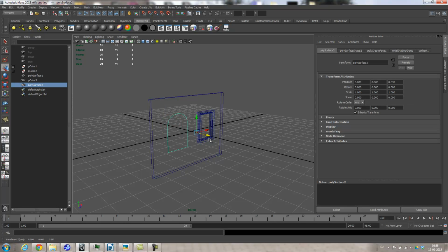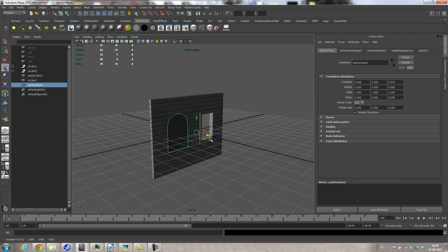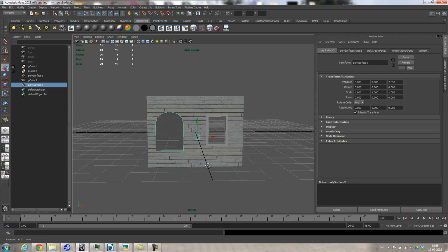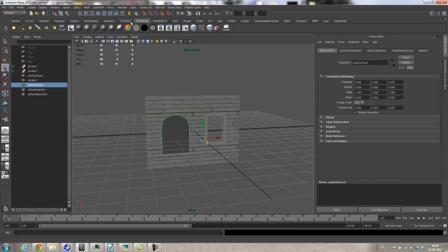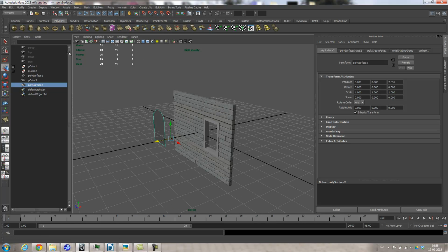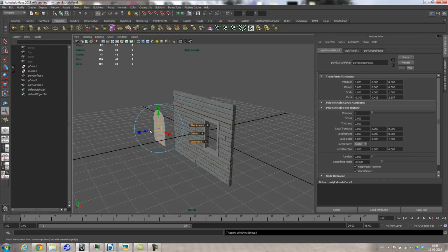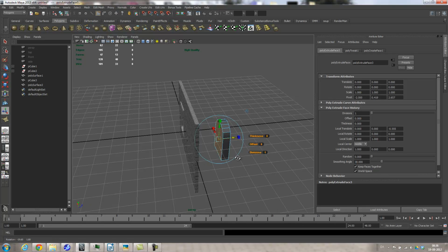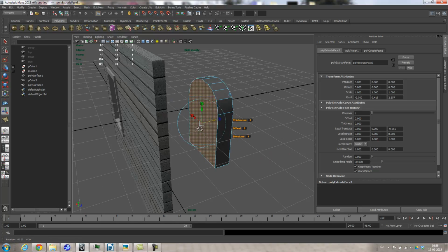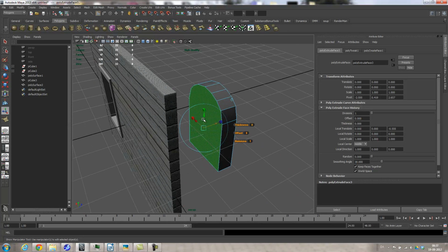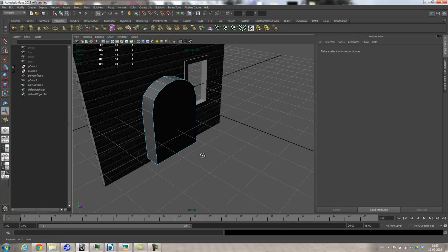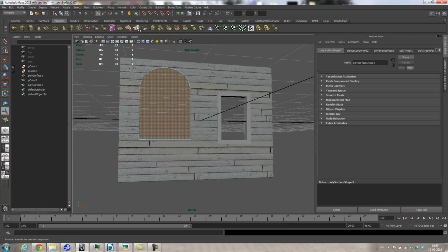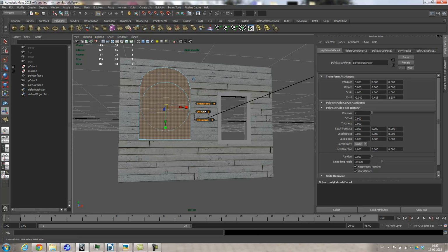Drag it out here so you can see that this is just one plane. And if I then go and extrude this, there you go. We get a little bit of depth. And this time I'll try to do it without all of the bridge thing, so I'll just delete the backside. There. Grab the front, extrude again, do a little bit of an offset in.